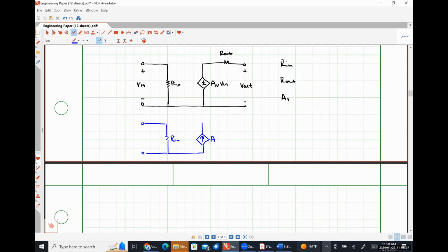So this is going to be a transconductance gain, so I'll call this AG. What does this look like? Well, if I call this guy right here, maybe my base, and this guy my collector, and this node down here my emitter, it's effectively exactly the small signal model of our BJT from the jump. In a MOSFET, we have already explained that our input resistance is effectively infinite, so we would just replace that with an open circuit. So this small signal model, or this practical amplifier model, is effectively already directly in front of us.